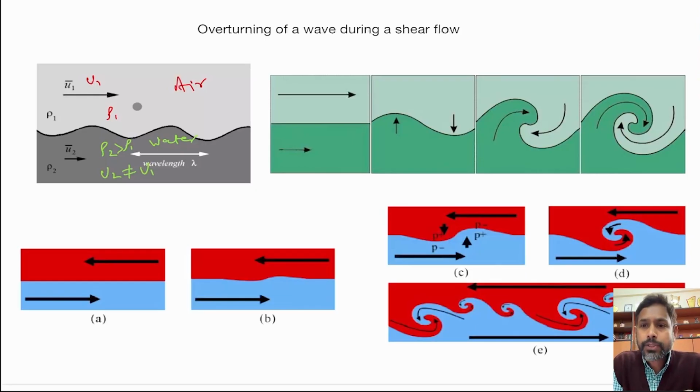So now there is a shear force or shear flow in the system because these two fluid layers are moving with different velocity, right? And what exactly is shear flow? Whenever there is a velocity gradient in the transverse direction, and what is the transverse direction here? We are assuming that this is the major direction of the flow, like both the fluids are moving in this direction horizontally.